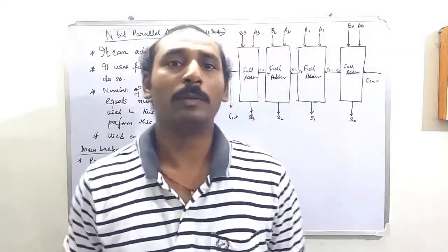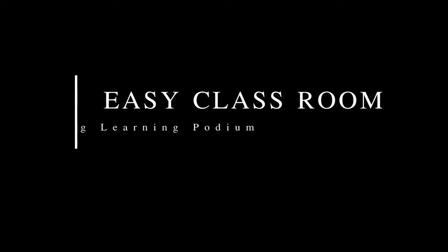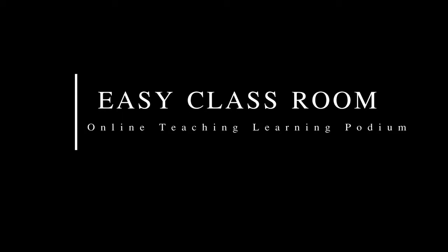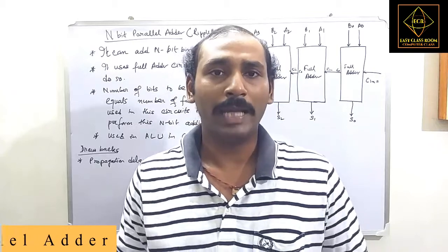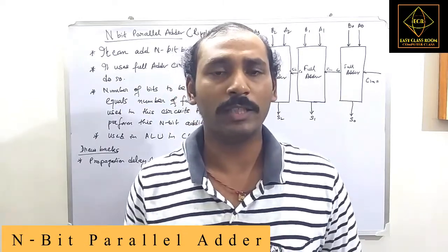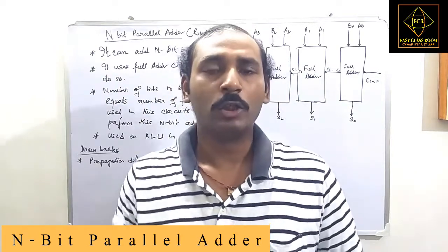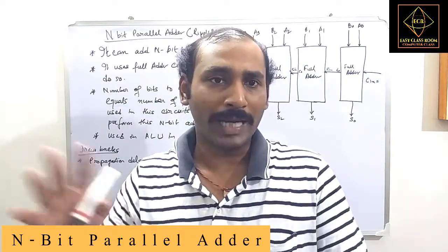For today we will be learning n-bit parallel adder. For an n-bit parallel adder we will be adding n number of bits with the help of full adders, because a full adder has the capability to propagate the carry information for us.